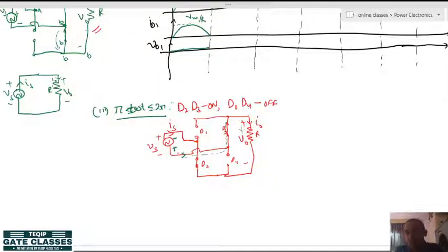Here you follow, you see that the load voltage and load current references are still followed. You just trace the path, this is the value of supply plus here minus here, and so the source current is going like that, going from D3 to load. When it is going through the load, again you see the load current and load voltage references are followed. So, when the references are followed, it means the load voltage and load current both are positive, and again it will go to D2 and then back to source.